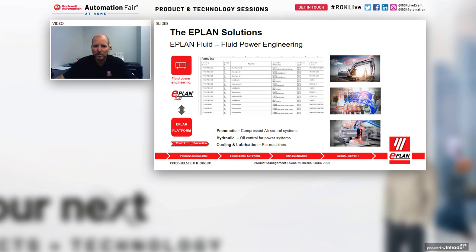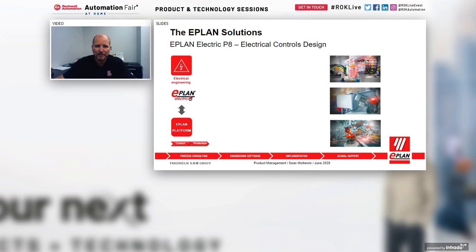Finally, you can use Fluid to also generate bill of materials. So with a click of a button, I can generate all of the parts that are associated to my design. So we don't keep the bill of materials separate from the design environment. They're all integrated into one environment. So if you're missing something in the bill of material, that's probably because it's also missing in the design. So it makes sure that you are accurate in your design and that you're not missing anything. It keeps track of the information in both environments, bill of materials as well as design.